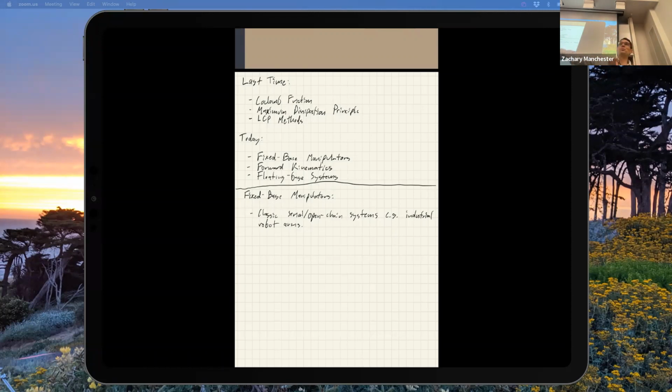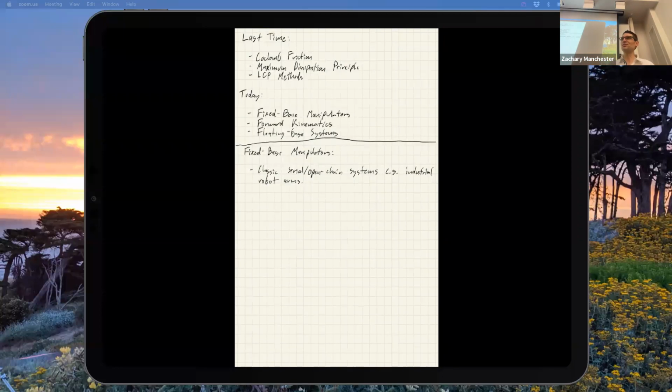You have to unroll the loop, write the dynamics down as if it were a serial chain, then add a constraint outside of the main dynamics stuff, the RNEA stuff, to pin it back together, which is annoying. So that's what's going on there. And we'll talk a little bit more when we get into these fast algorithms why that is a thing and why it happens. It's not too hard to see where that comes from. Yeah, I guess that was a long diverging discussion on what these are.